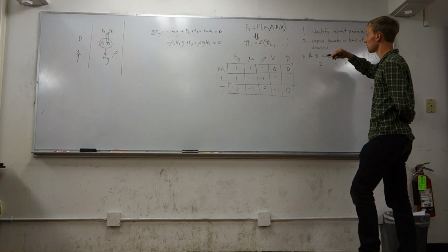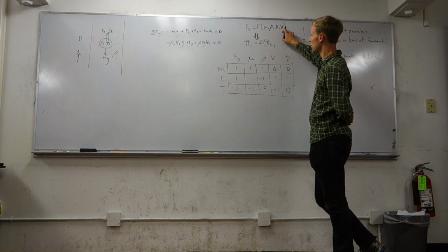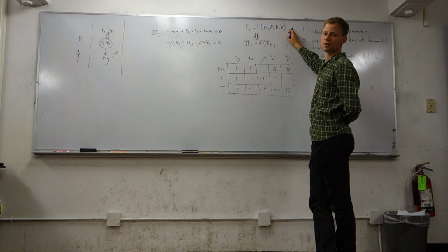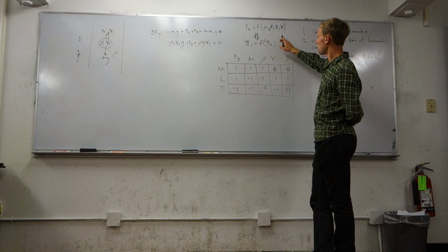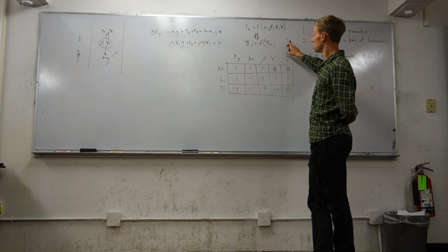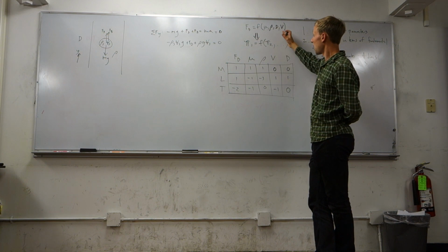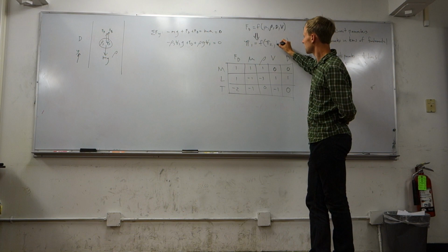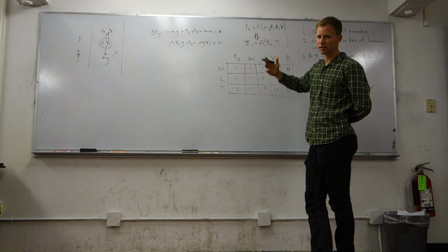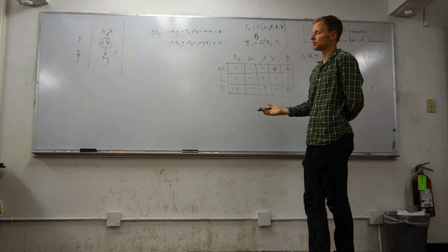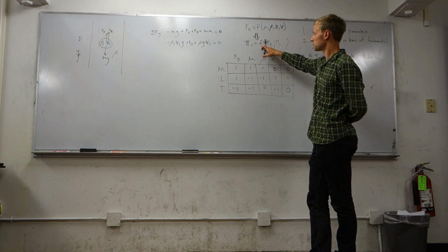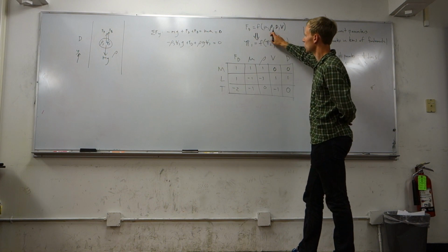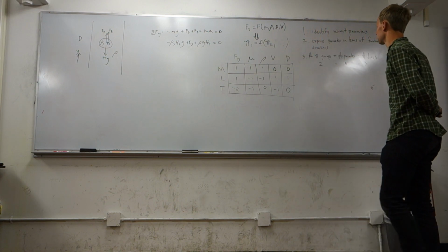And of course, note here that we could be adding other variables that might be relevant for our problem, such as the temperature of the room or the atmospheric pressure. And that would be fine. We just introduce more pi groups. But what would end up happening is, if they're not relevant, and we've made a mistake, then the functional dependence on pi 3, for example, if it existed, would be minimal. It would be some small number times pi 3, for example. So that will drop out in our experimentation. We do not have pi 3 because we're being smart about which parameters we pick that are of importance.